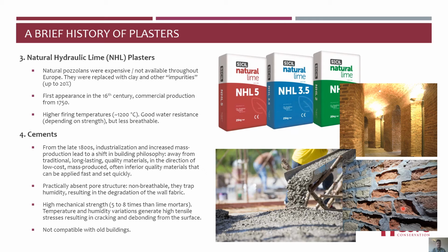It doesn't mean cement is a bad material. No, it's not. It is just a different material. It has its applications, and in certain areas, they are first class, but in old historic buildings, they are just too strong. They block moisture, and as a result, they are not suitable.